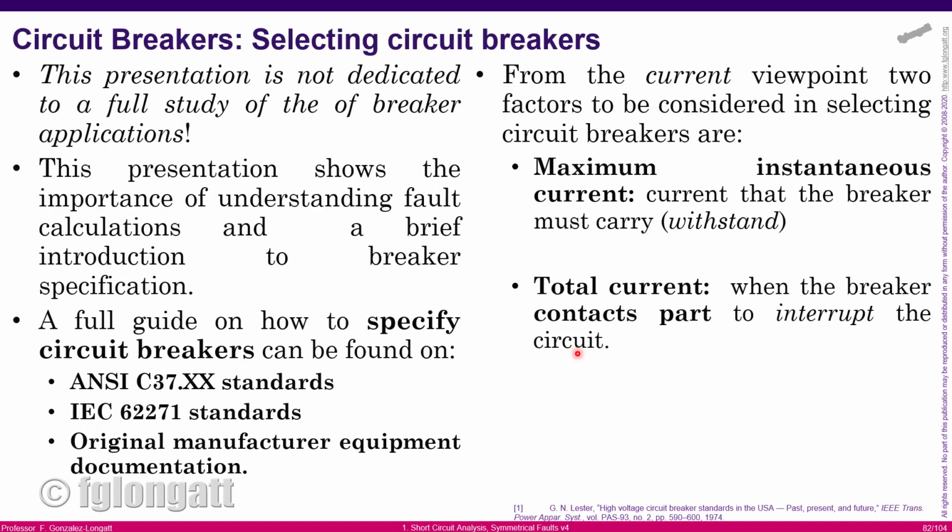This presentation is only to show you the importance of understanding how you connect the fault level calculations with the specification of circuit breakers. A full guide on how to specify circuit breakers can be found mainly in standards, but the standards are generic. What I suggest is, if you are working with an ultra high voltage or extra high voltage circuit breaker, go for the original manufacturer equipment documentation. There is more data over there.